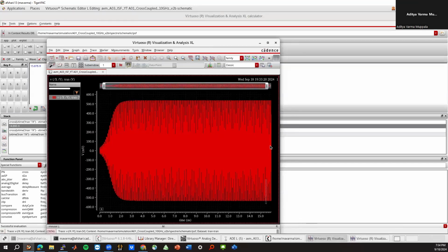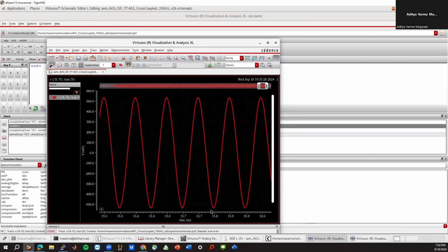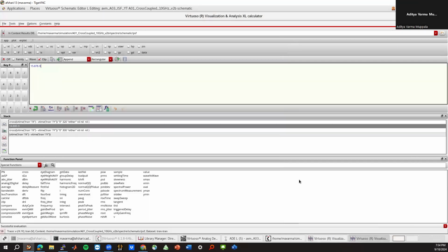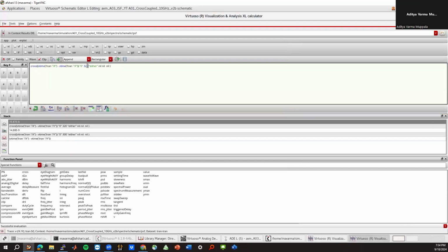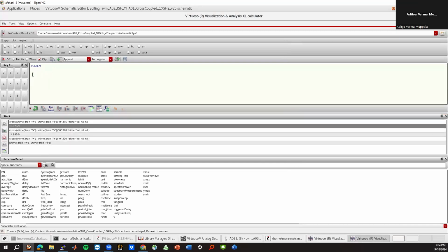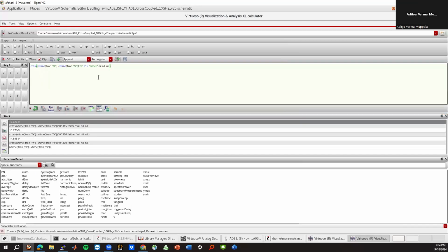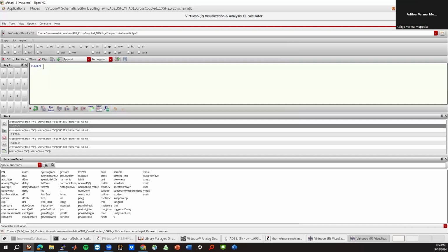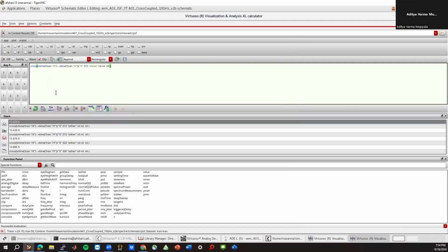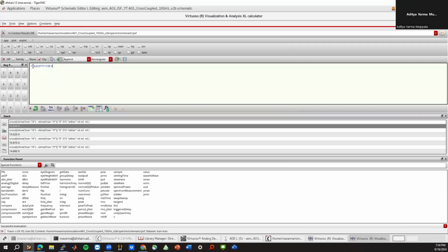So that's very close to the end, right? We don't want to be too close to the end, so maybe I'll reduce it a little bit. About 315 sounds good. Okay, so that's very nice. We'll use 315 for now. And if I actually evaluate this number, it gives me 15.62. But I want more significant digits, right? What you can do for that is go to options, significant digits. Let's say I take about 12 significant digits. Now I'll recalculate this and it gives me 15.62237, whatever.